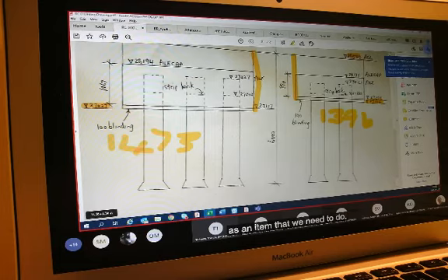Okay. We then have one of our favorites, keeping excavations free from water, and that's measured as an item that we need to do. So now I will have to measure the concrete that goes in there. As I look at that drawing, I can see that there is concrete in there, and concrete is separated in 2 sections.